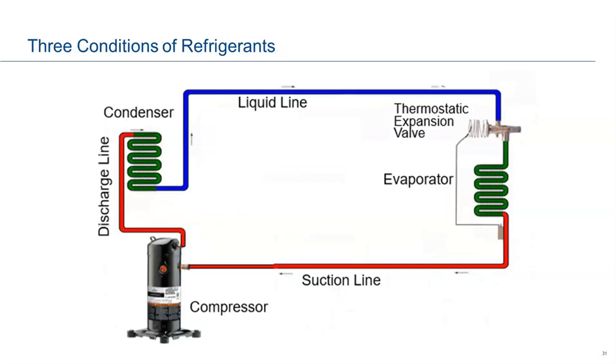So to bring it to a head here, we said saturated refrigerant there, okay? We're changing state, which is latent. We're changing state but not changing temperature. We'll find that in our condenser coils and our evaporator coils. We're going to find superheated vapor here in our suction line and our discharge line. I want you to remember, like our ball diamond, remember this. This is low pressure superheated vapor in the suction line. It equals low pressure superheated vapor. On the discharge line, we're talking about high pressure superheated vapor. So there is a difference, okay?